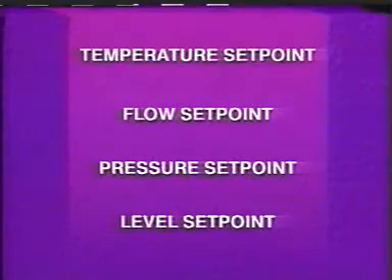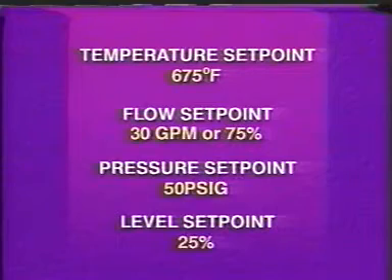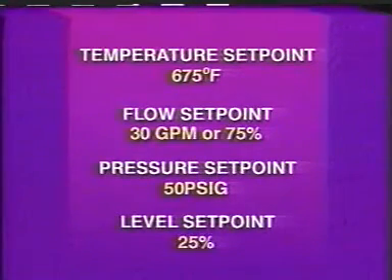In every control situation, it is assumed that there is a desired value for each process variable. This appropriate value, or range of values, represents the best available operating condition for each variable at that particular process. The desired value for a process variable is usually called set point. Here are some values that could represent set points for some process variables. We usually express a set point value as a specific number or as a percent of a particular number or range of numbers.